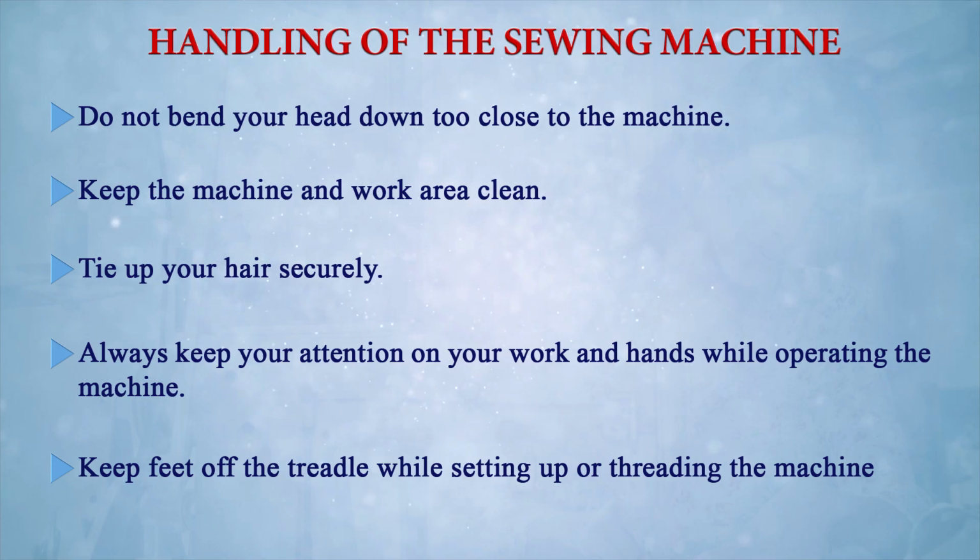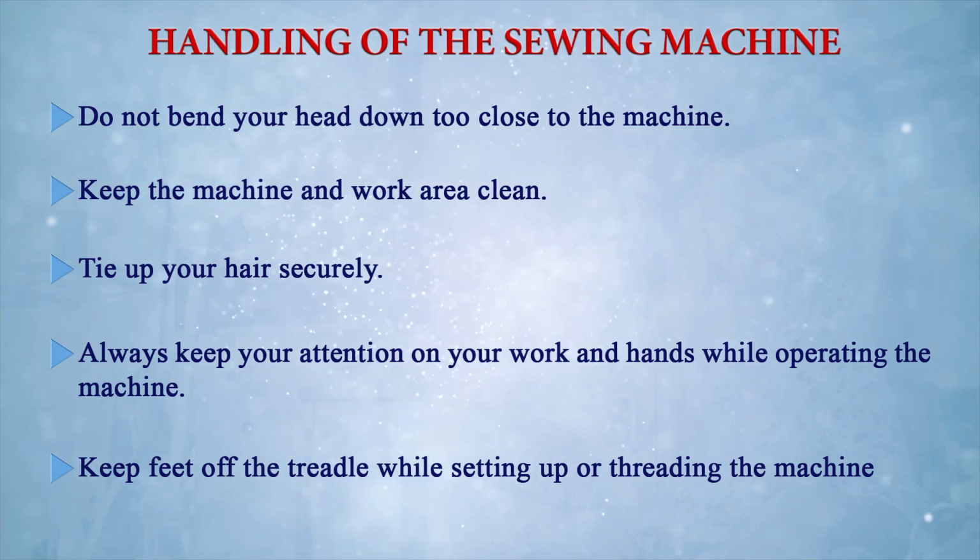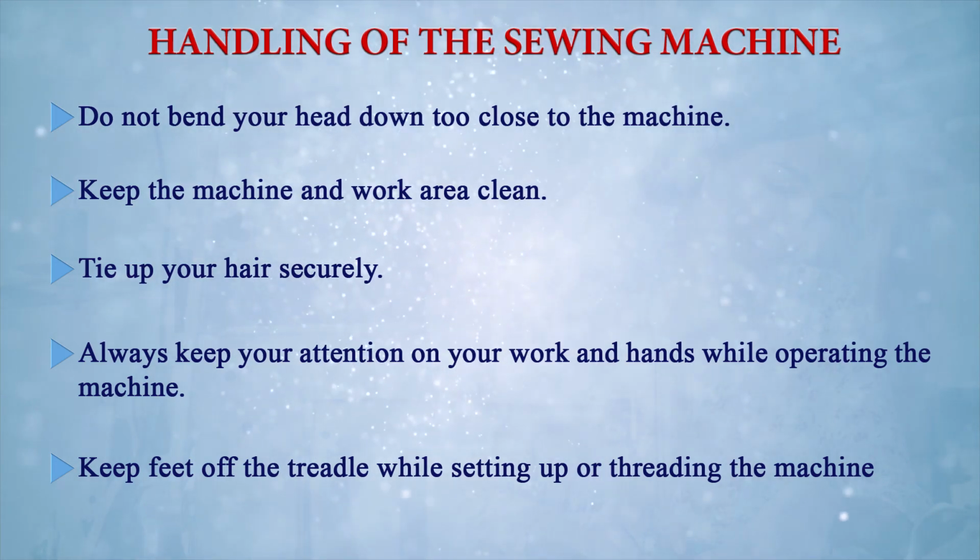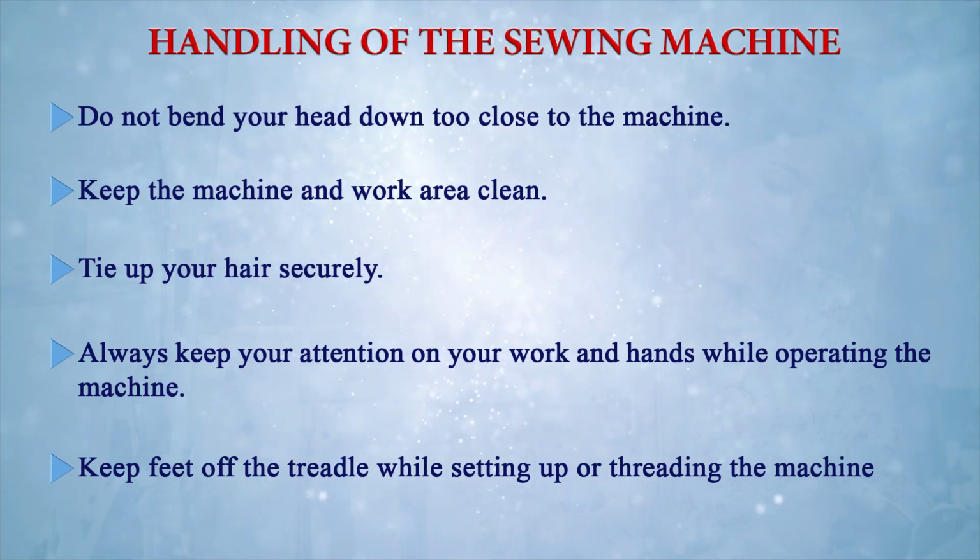Then keep your feet off the treadle while setting up the threading on the machine. When you are setting the threading, keep your feet off the treadle to keep it very safe. Then do not pull the fabric backward in order to stop at a particular point.